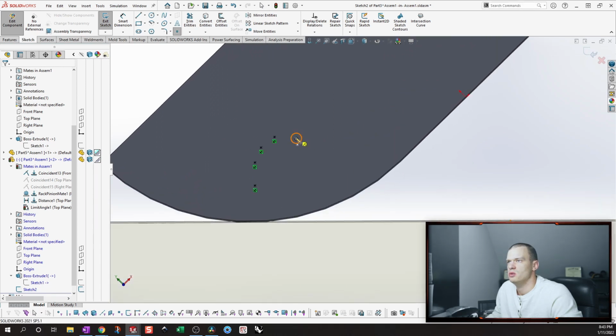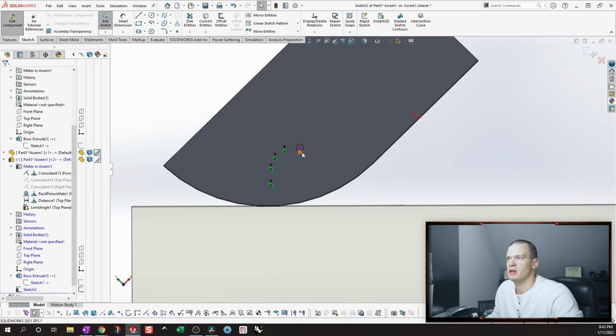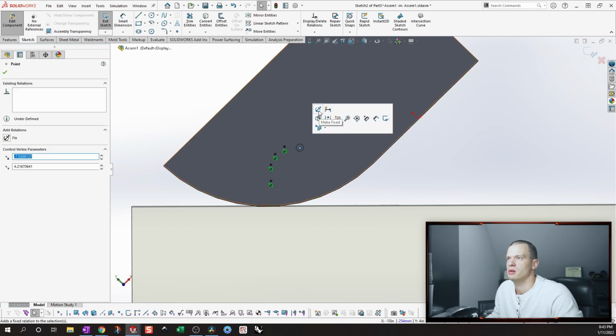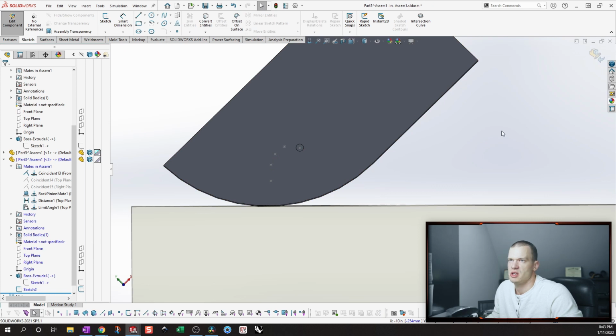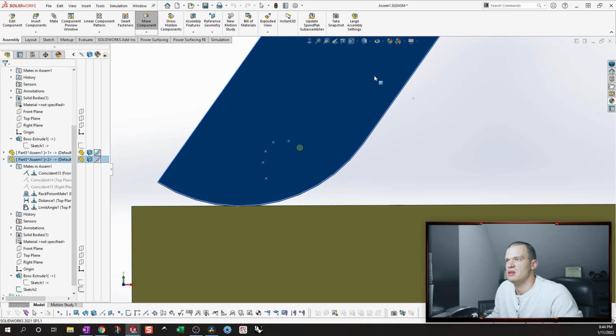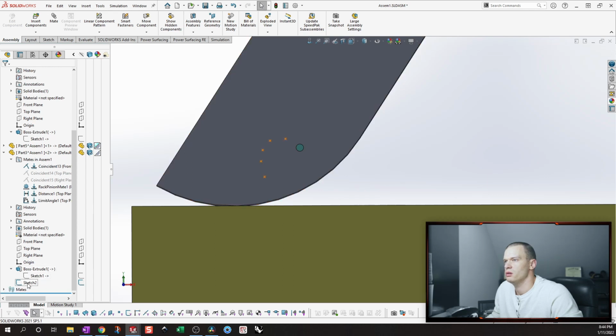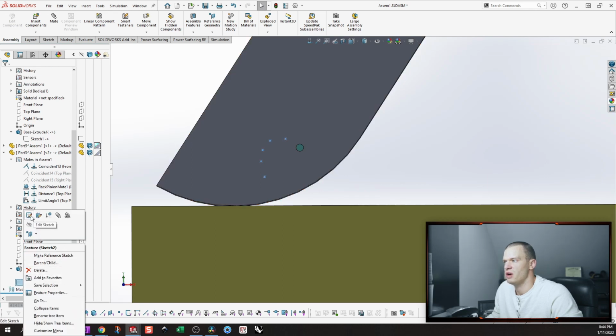And 2, tracing that slot, since there's nothing else based on the slot, there's no other geometry or part that you're trying to find from that slot feature, you could probably solve it fairly close to the end of your model, or you could do this as a last step in modeling and then just cut your slot in as the last feature practically. And it's not going to hinder any of your other parts or design or process.